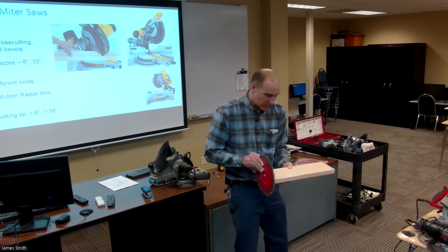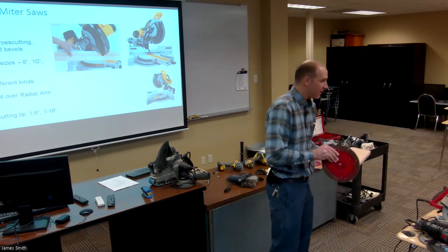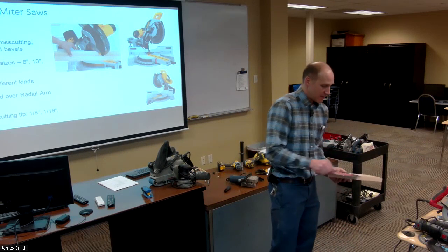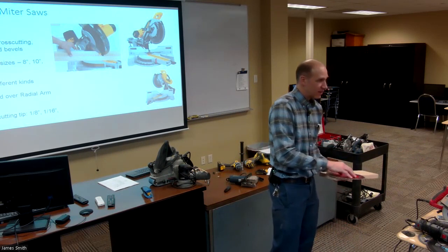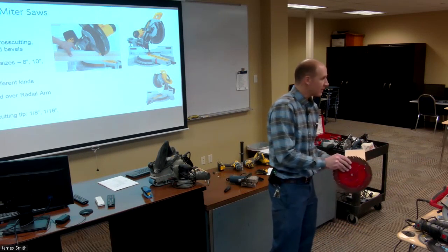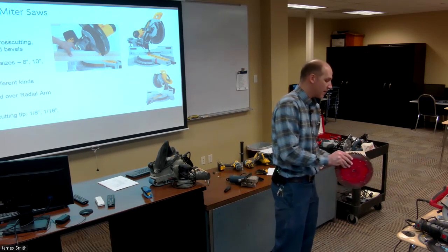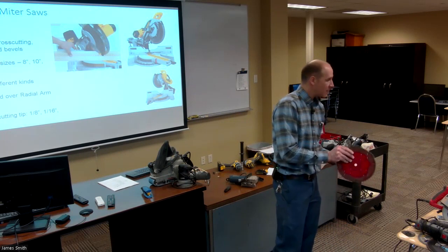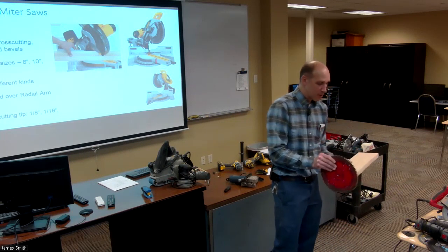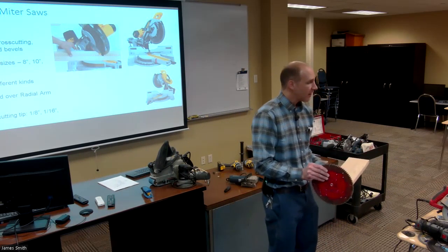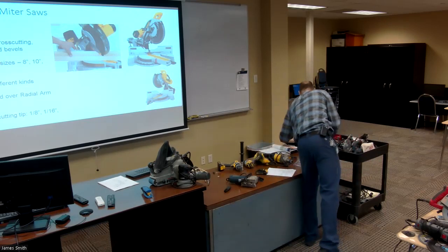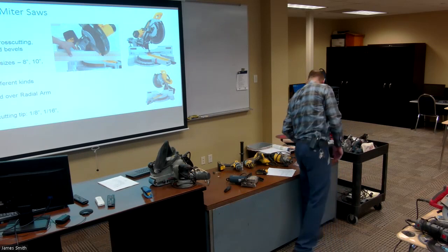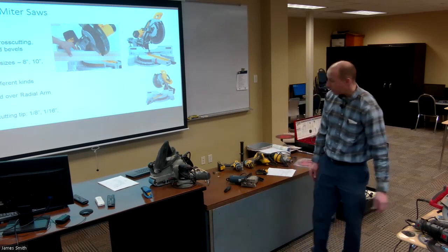What that does is it takes off the thickness of the offset between the carbide teeth and the inside of the body, which is about a 64th of an inch. It's not very much, but if I'm trying to get it to fit just perfect, I'll use that as a means of measuring and cutting off just a smidge. So that's a nice little trick. Okay.